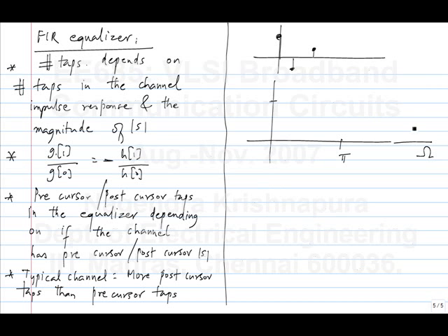And you have an FIR response. So you have 1, right? The DC gain is 1 plus alpha, and the high frequency gain is what? 1 minus alpha. And if alpha was negative, it would look this way, isn't it? And this is the kind of response you want. So the first tap is invariably negative. The taps after that you can't say.